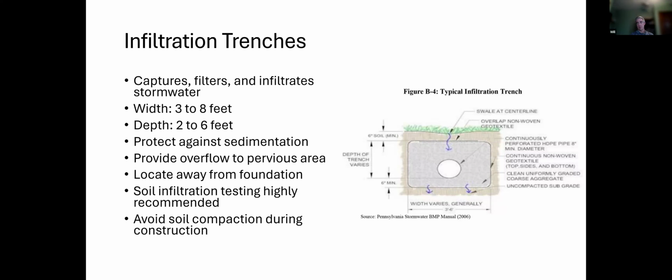So we just look at column one here, where we want to treat 200 square feet of impervious area. And using this spreadsheet, our rain barrel or our cistern needs to be at least 166 gallons. And again, this is assuming that it's about 25% full on average. So that could be 3 55-gallon barrels in series, or you could buy one larger cistern and use that instead.